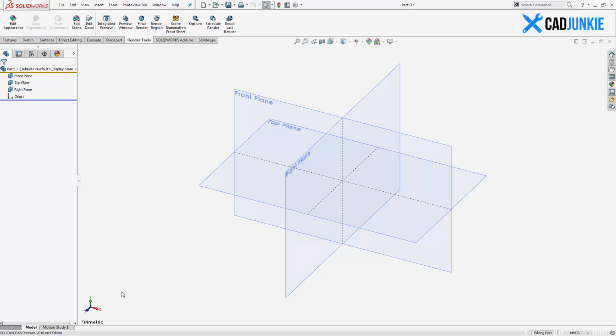Now, that is possibly an overstatement, but the point is that you may be tempted, of course, as a car enthusiast, to want to rotate things in SolidWorks so that Z is up and X is forward. Now, you can do that. You will see various people give tutorials on how to rotate things using this button right here, Update Standard Views. You could change it so that the Z-axis is now your top view and the X-axis is your front view. That works. It's okay to do that, but it's going to cause you all kinds of headaches down the line.